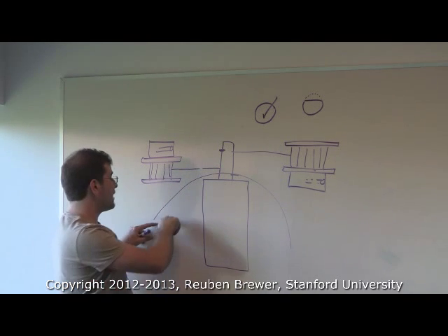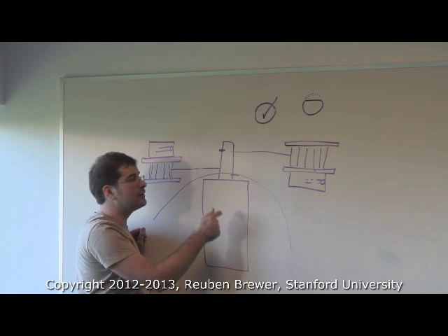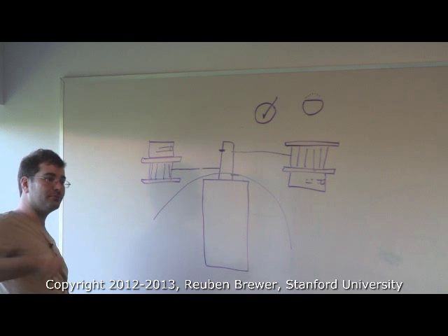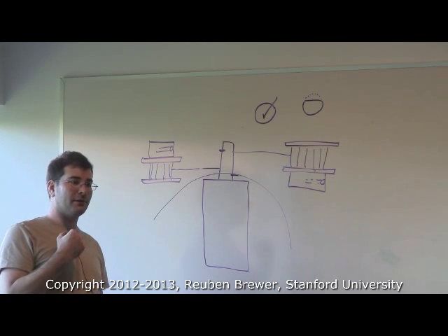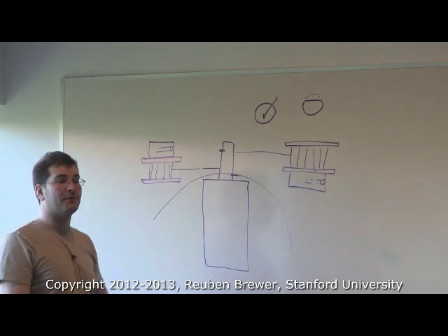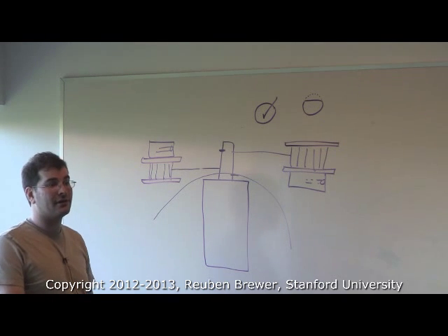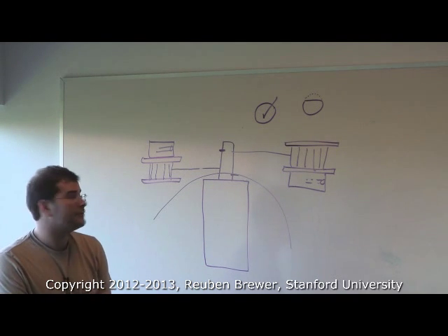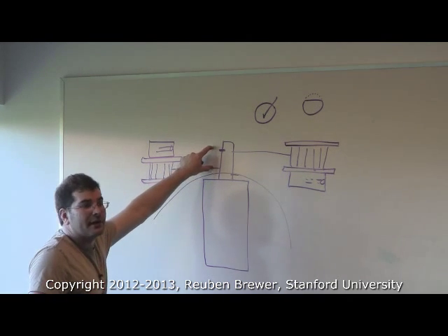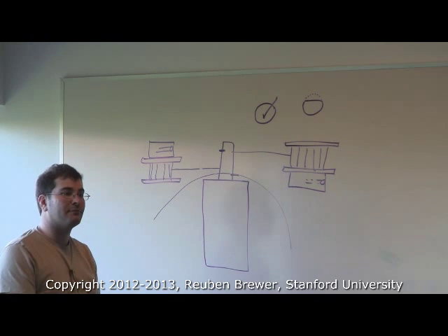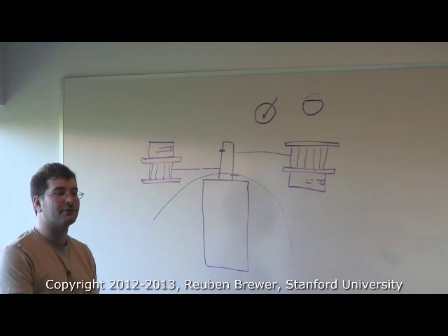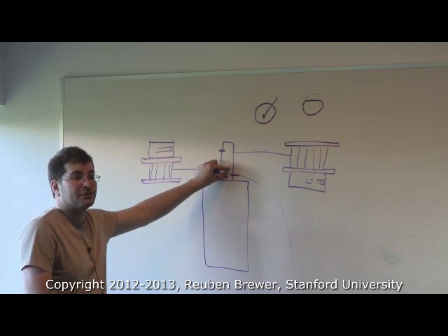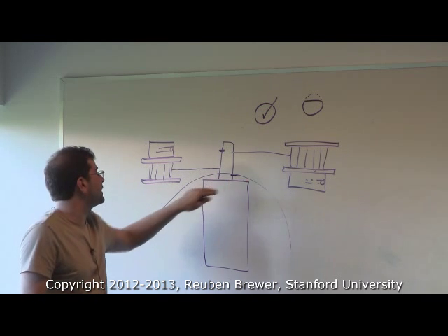One reason is you have to put plastic around all this and tape it down. The closer you get here, the less distance you have. What I do is take compressed air and blow it on the shaft while I'm doing it. I've also seen people dunk this in water quickly to cool it. Basically you need room to work here. If your bag's right here and you're dremeling right on top of your bag, you're increasing the chances to screw up and get particles in your bearings. So you're right, you could just dremel this little section. It's just more dangerous. So let's go over this again.